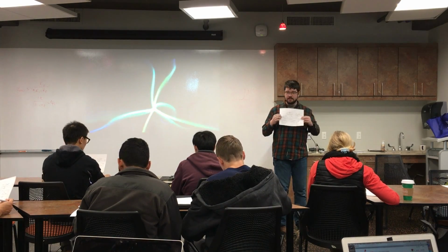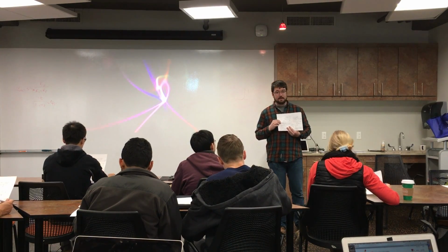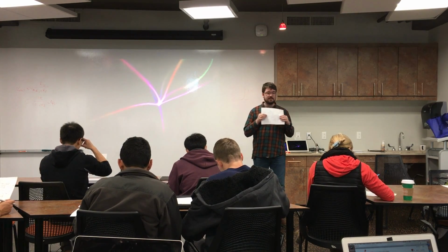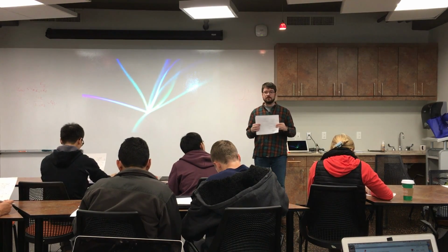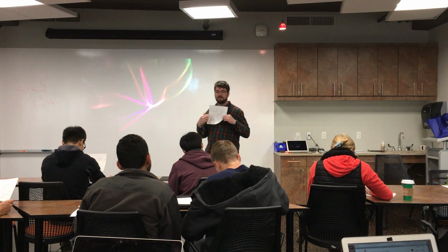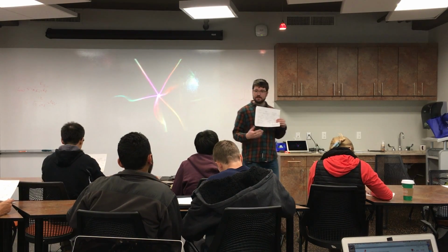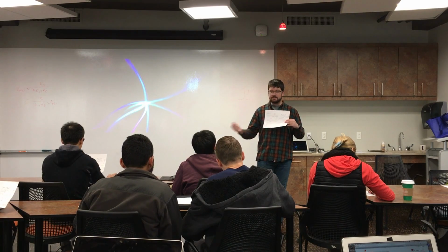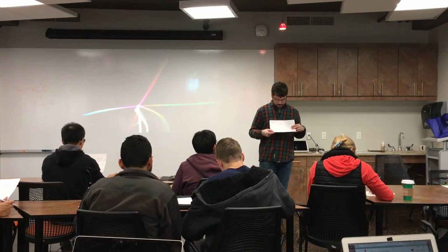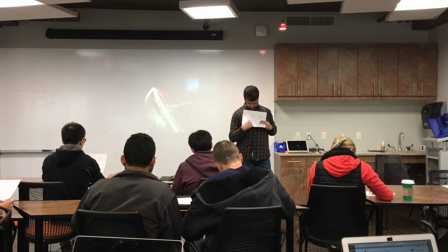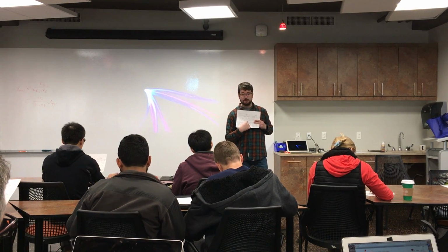So in this case, we've got a DCDT, LVDT, labeled on here, differential input coming in, going to this INA105. So that's serving as a buffer, a one-to-one buffer, so we don't load down that instrument, and we have a low impedance output. And that's going into another INA105 as a single-ended input to the non-inverting terminal.